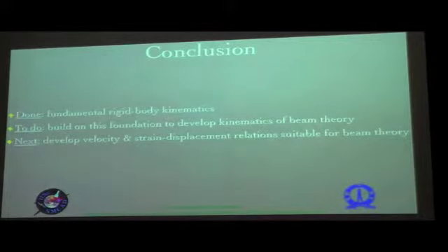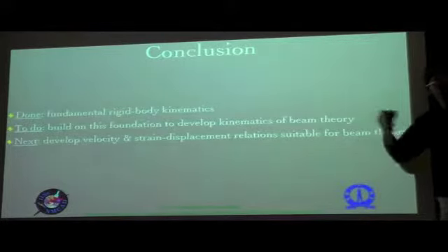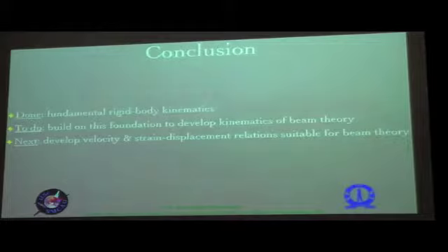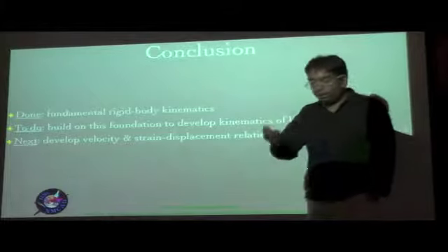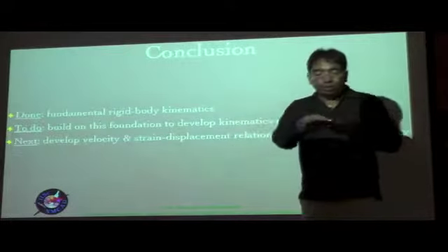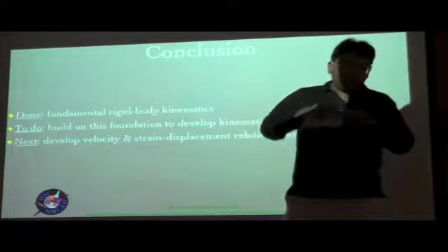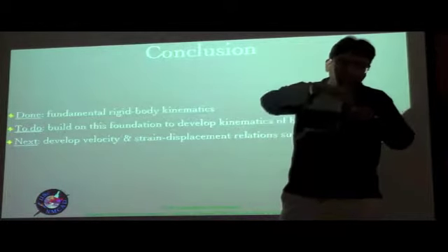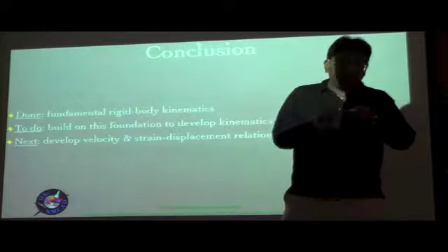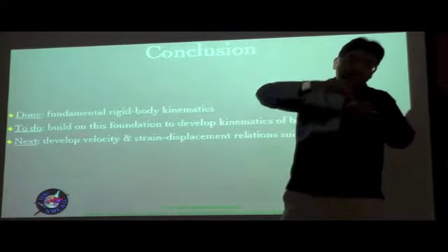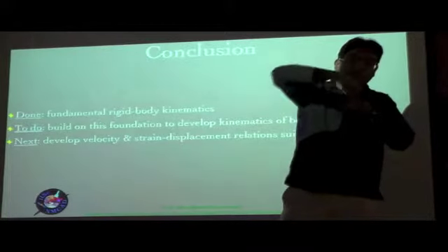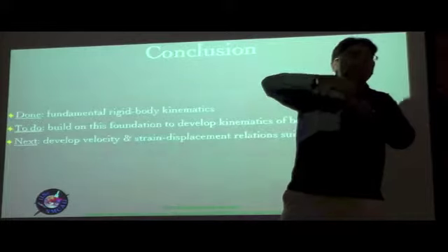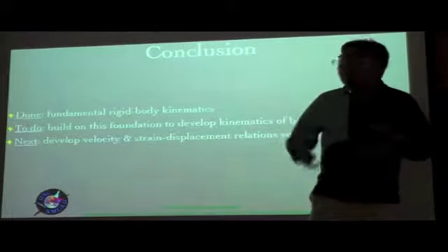The displacements, of course, are the translations of the cross section, and the rotations are the rigid-body-like rotations of the cross section. In turn you would have the warping variables, which again can be divided into two parts. For example, if you're talking about a strip like this, then you can talk of the average warping along the thickness as one of the translation variables of those line elements, and then you can talk of the rotations of those as the local rotations. The rotation about the one axis and the rotation about the two axis will both be local rotations.